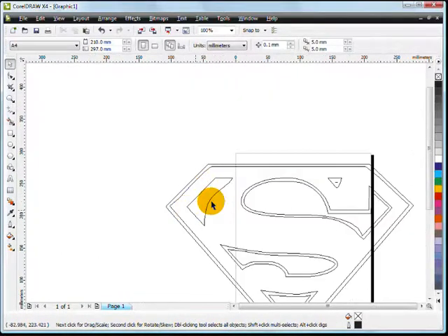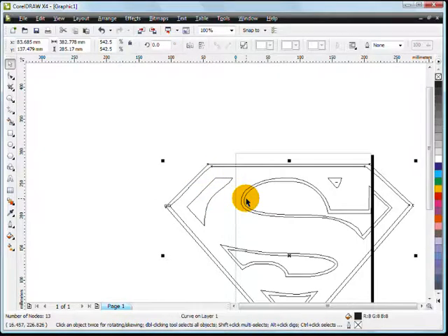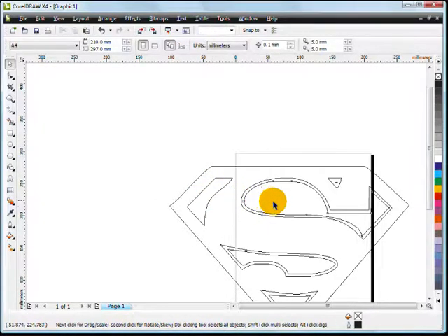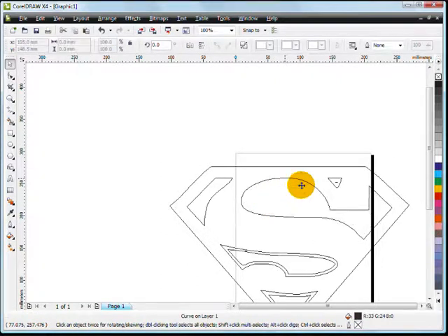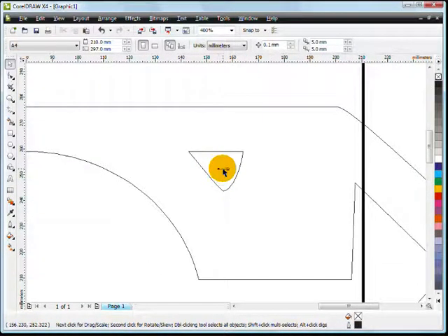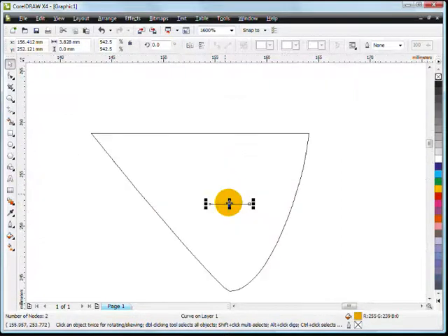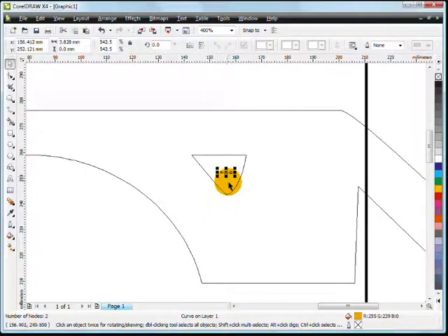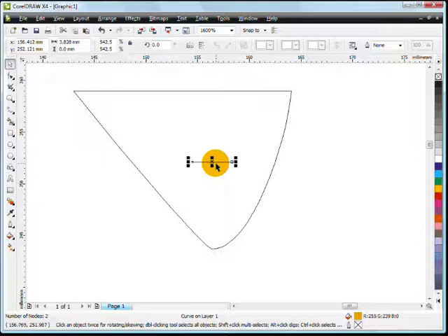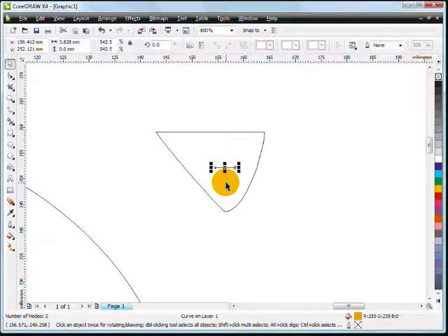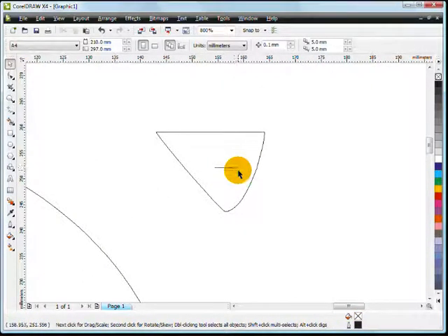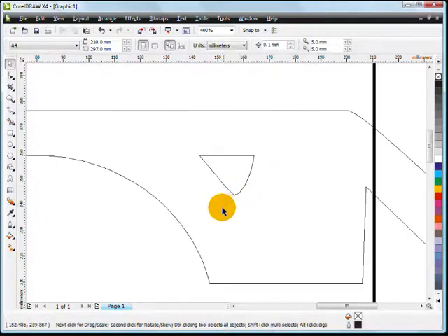So I'm just left with the outside. Once again, I select the outside one, left with the internal, and here select the internal one, then we'll select the black line. Can you see in here there's a single line? It's very hard to see, but if you leave them there, the machine will try to cut them. So if you see the machine behaving weirdly when you're cutting an imported design, I bet if you zoom in you'll find that there's some evidence of a stray object there that you didn't want to cut.